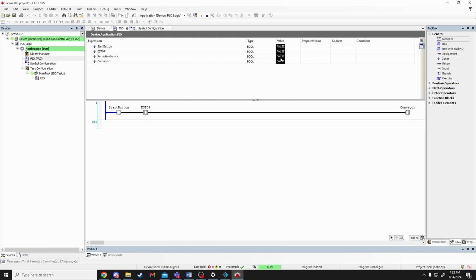And we can change our variables in here. So if I click the start button here, I went over to the prepared value sections and just clicked that once, and it says true. The keyboard shortcut for updating that value now to our PLC is Control F7, and you see that the power has moved one section of this branch further. eStop. It's not working yet, but it will work when we have it hooked up to FactoryIO. Just have to wait and see.